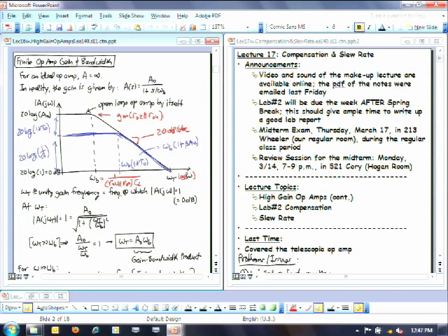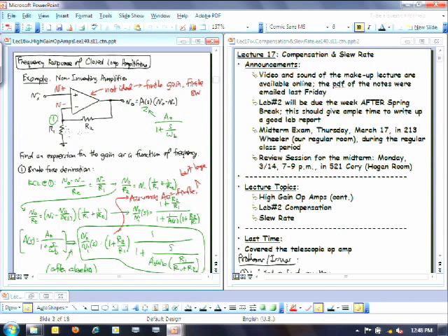This is actually something we did on Tuesday of last week, this Bode plot stuff. And on Tuesday of last week, we actually ended up here, where we were handling this non-inverting amplifier, except we were now interested in how it performs with a finite gain. So instead of an infinite gain, it has a finite gain.